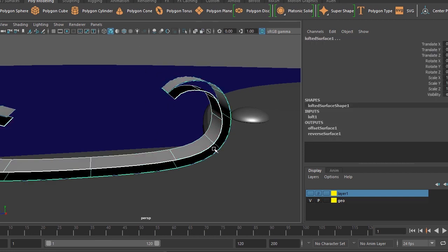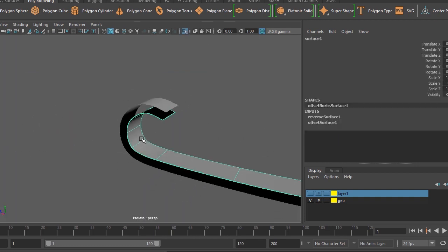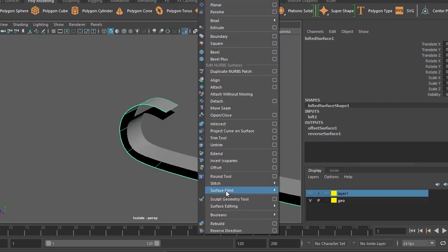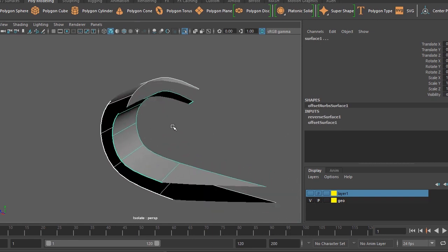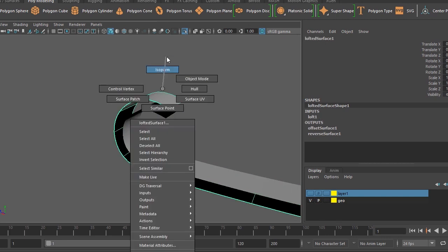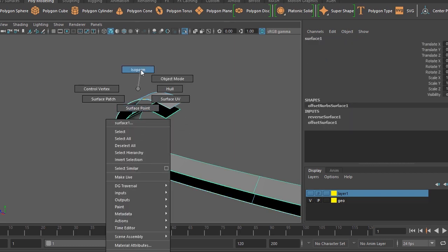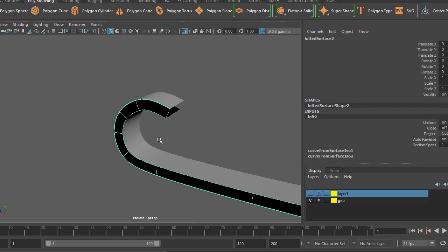Okay, now select both of them and try to connect the geometry between them. How do you connect is, see, first I selected this model and I went on to do offset, and I got a model with the offset, and the offset value was minus 0.05. So these two are separate pieces. Now in a NURBS model, if I right click, you have a component called isoparm. So select that isoparm here, then hold shift, then select the isoparm of this one, and then you apply loft, then it will create geometry between them.